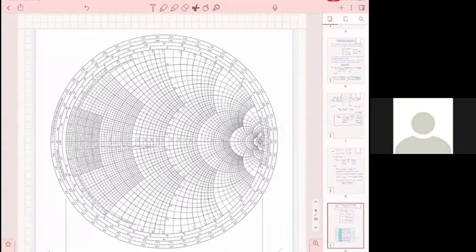But let's do the first one you said, which is to find the angle, -175. And you remember, these are reflection coefficients we're looking at, all right? So which ring of all of those are you going to start looking at? You are going to start looking at the ring that says angle of reflection coefficient.